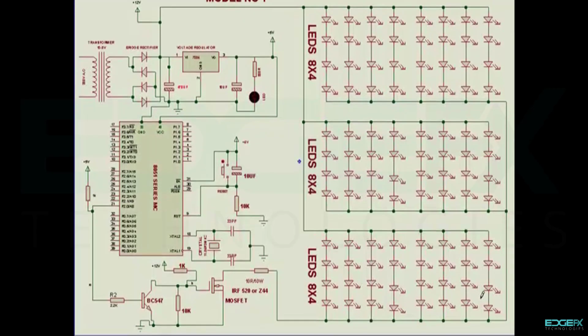In this circuit, auto intensity control of street lights, we have used a number of white LEDs for the street light purpose. Usually street lights use high intensity discharge lamps, for example sodium vapor lamps, mercury vapor lamps and metal halide lamps, which have difficulty in starting time, whereas switching over to LEDs could be much better in the sense that it switches on instantaneously. And it can also have dimming facilities.